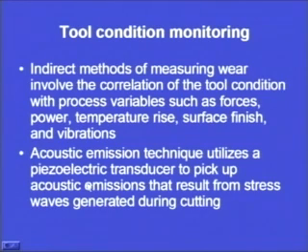So, the acoustic emission technique utilizes a piezoelectric transducer to pick up the acoustic emissions that result from the stress waves generated during cutting.